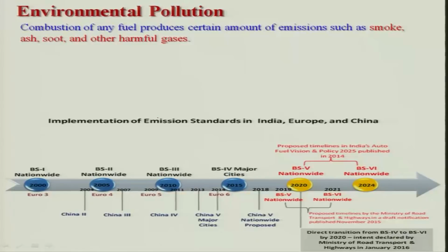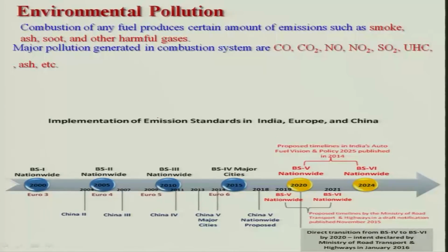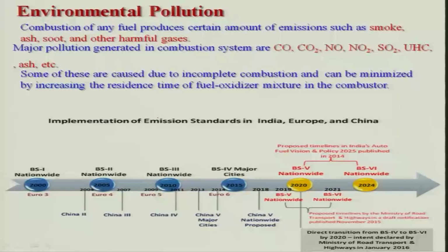And the major pollutants generated during combustion, what are those? Basically carbon monoxide, carbon dioxide, nitric oxide, nitrous oxide, sulfur dioxide, unburnt hydrocarbon, and others. Maybe ash, then smoke, then soot particles. All those things will be coming, but those are causing a lot of problems.